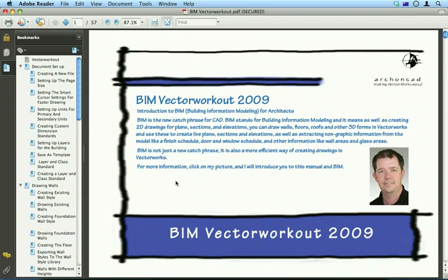So, what could it be? For example, we could use a wall. A wall has a 2D component, has 3D stuff, and you put holes in it with windows. Vectorworks knows the area of that, so you could extract the area off the wall because Vectorworks knows the total surface area less the area of the openings. You could also attach information to that wall, like the insulation value, what the cladding material is, and then you can create a report from that.